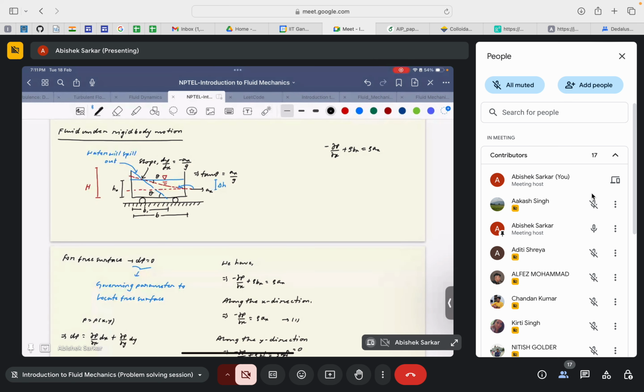the surface forces that act on these particular fluid elements are the same in the case of fluid being stationary or fluid moving in a way which prevents any kind of shear forces, or basically if it's devoid of any relative velocity changes between the fluid layers. Okay, since the surface forces remain the same in both scenarios, that's why we can consider this fluid under rigid body motion under the purview of fluid statics.